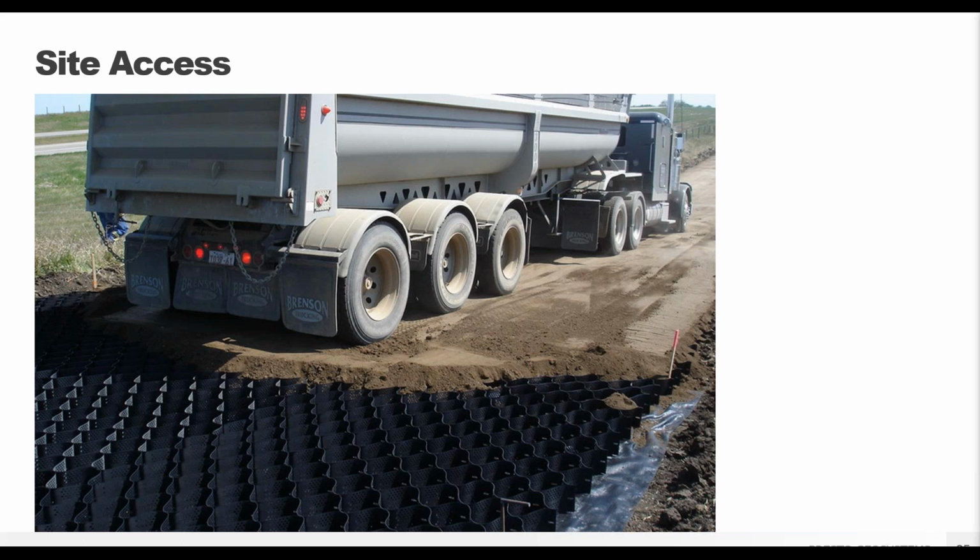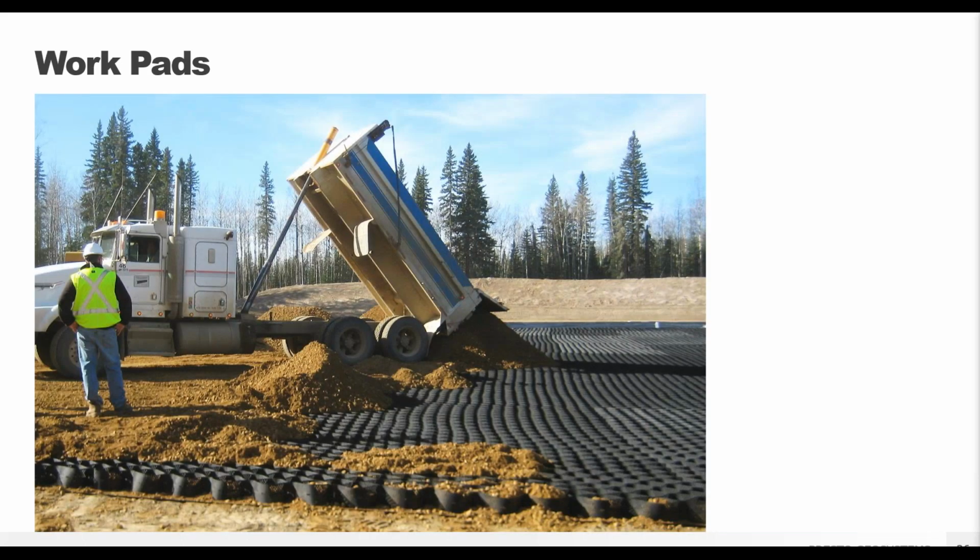This project was created to access oil resources over undeveloped, soft, spongy subgrades. And notice how there's a really heavy, loaded vehicle driving on the GeoWeb system immediately after infilling, to finish infilling further along the road. So you can drive on your road as your access road while you're building it. So you don't need temporary access roads built to the side just for construction. So definitely a huge construction time saver.